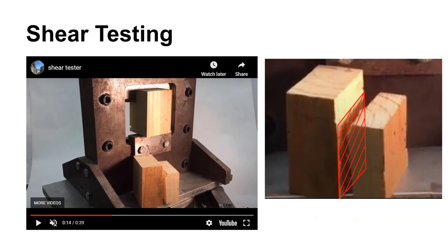The other thing is, if we have a stress-strain diagram that comes from a shear test, then that modulus of elasticity region would actually be the modulus of rigidity, or the shear modulus, and instead of being an uppercase E, it would be an uppercase G in most cases.